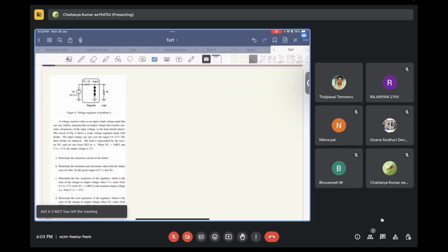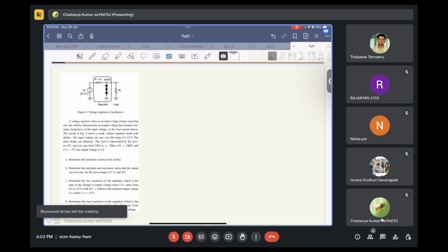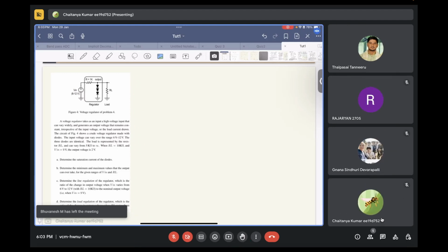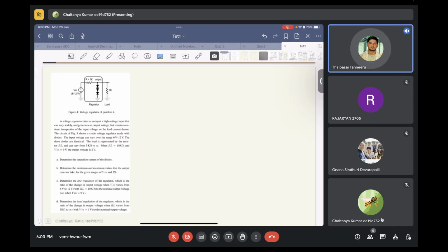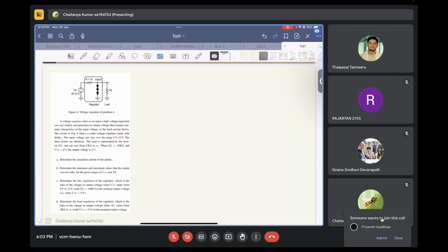While designing the circuits, mostly the circuits are non-linear in nature. All the active circuits mostly are non-linear in nature, and I think you guys know. Can any one of you answer why circuits are generally non-linear in nature? Because of the power amplification: if we don't have any non-linearity, we cannot get power amplification. We need a certain weak non-linearity to get power amplification. Correct. So you need certain non-linearity to get power amplification.